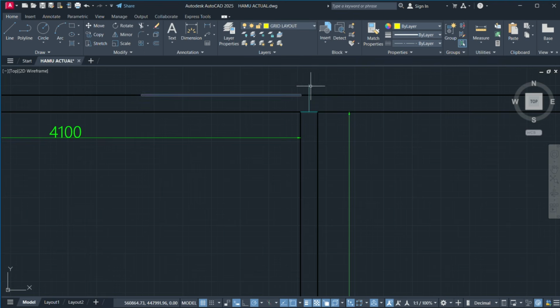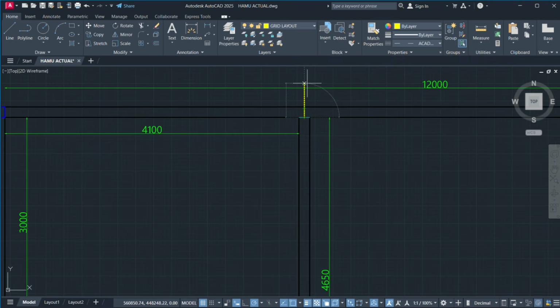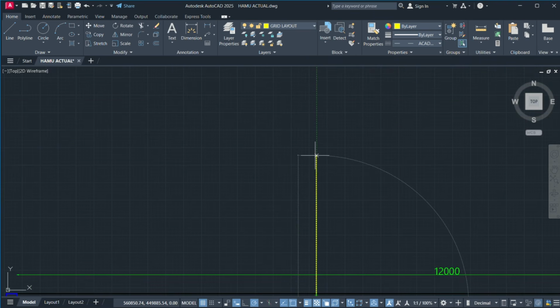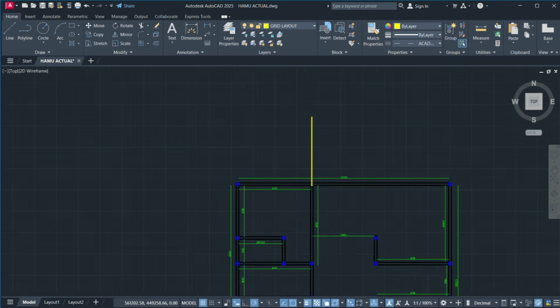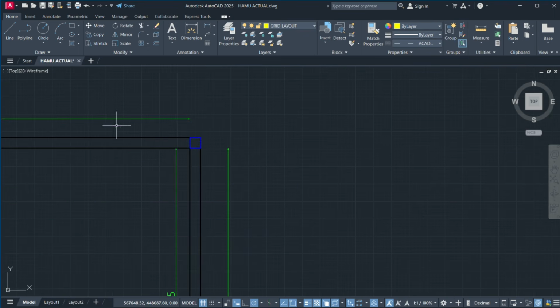Then when you select that layer, remember that your grids have to have a broken line type. So for example, I can use these broken lines that are here. Then I'll just create a line. Now these lines have to be uniform throughout. So for example, I'll create a line that goes up by 4 meters, which is just 4,000 millimeters. Enter. That's like this. Then I'll come over here to another corner and do the same thing. I'll do line, get this corner, and bring it all the way up to somewhere here.